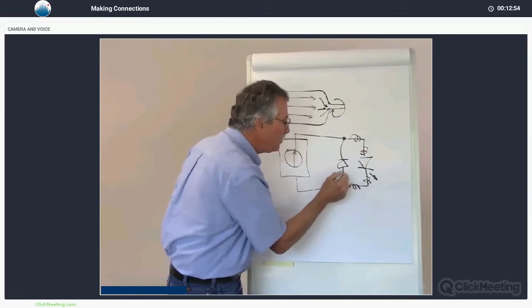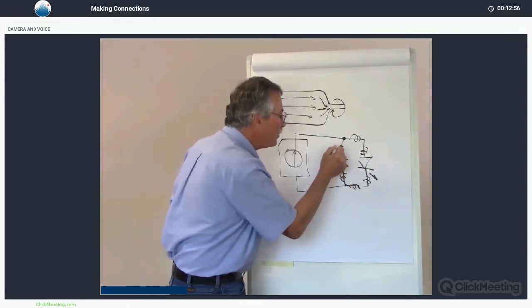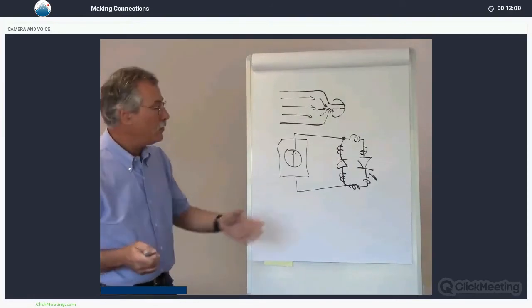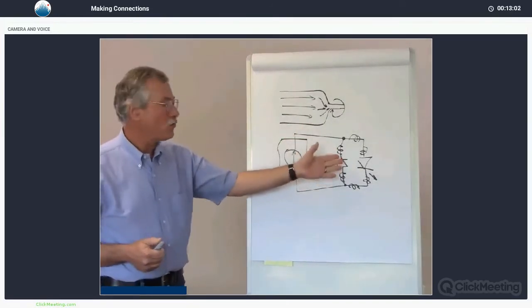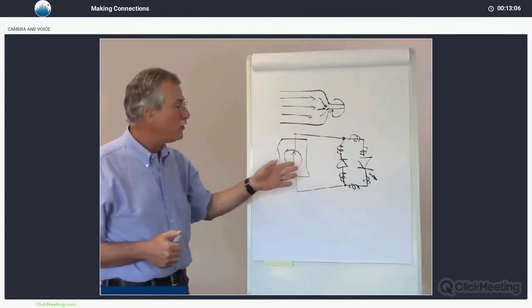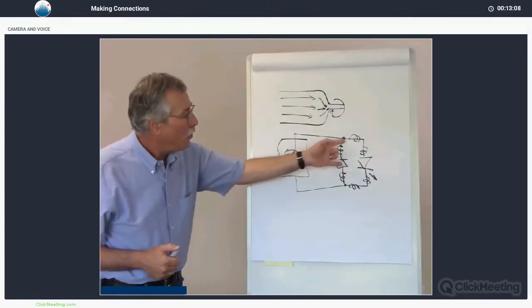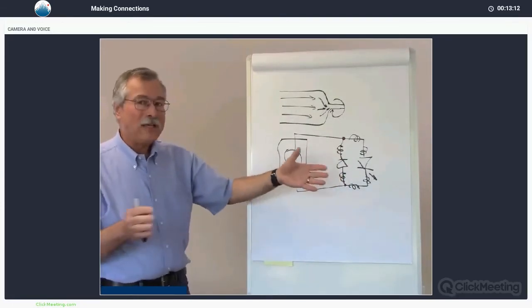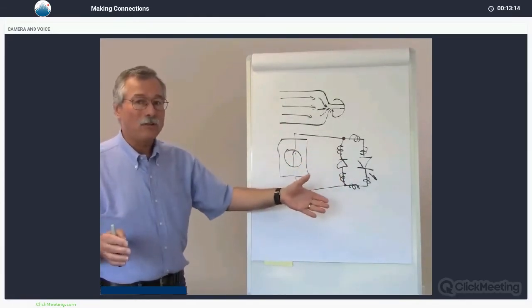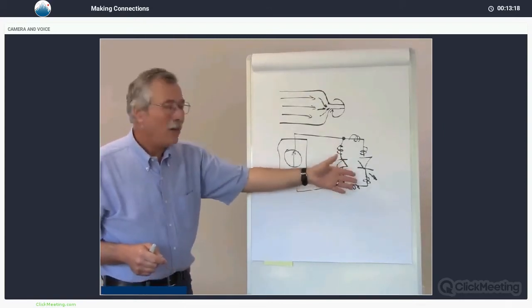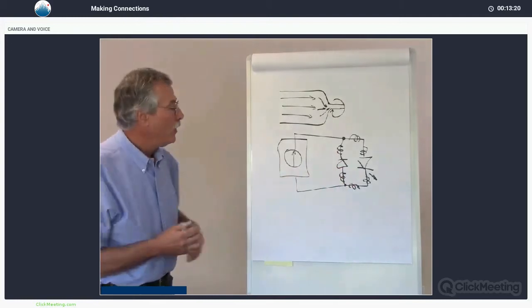The laser diode leads, any parts that we add to the output circuit. You might be inclined to add some resistance out here so that you can draw more current from the pulsar in case the diode is rated much lower than the lowest output of the pulsar. All these things add inductance. The inductance wants the pulse to lengthen. It wants to continue the current by opposing the change, and we end up with current flowing out here, which isn't doing us any good.